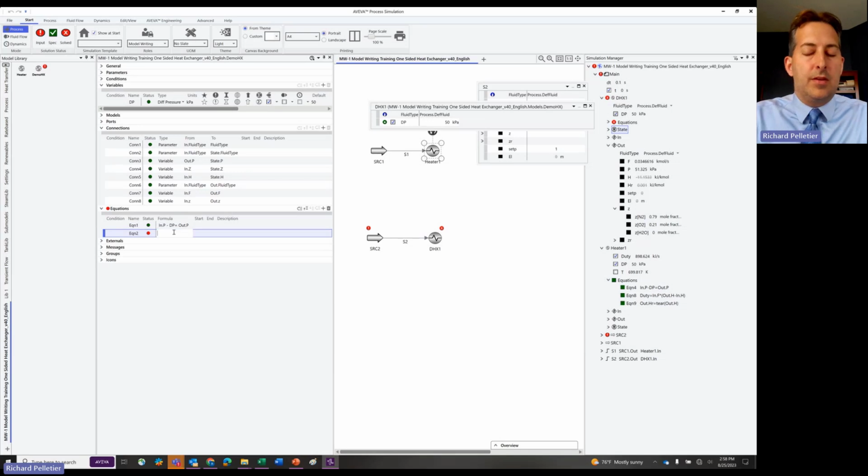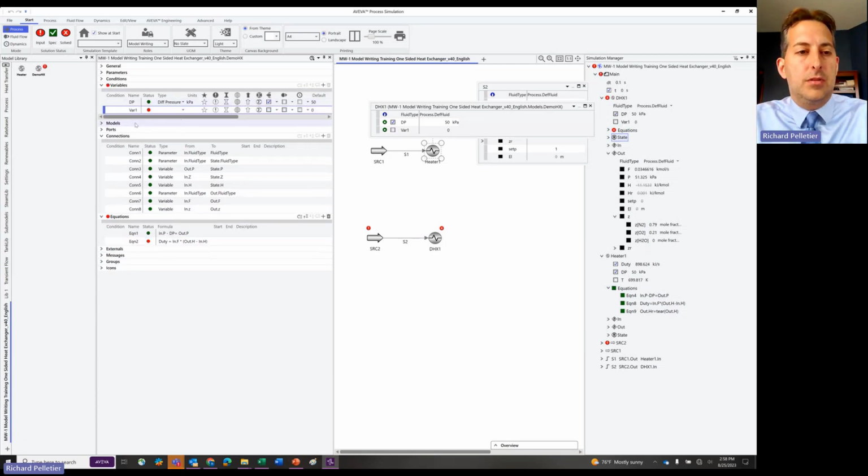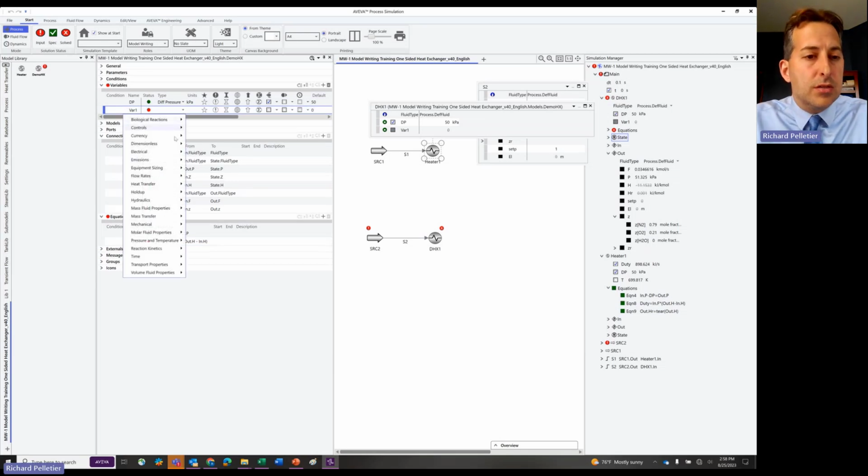We're going to type it out. Duty equals in.F times out.H minus in.H. Enter. When we do this, it tells us it's missing duty. Okay, so we need to go and add another variable. We're going to call this duty.